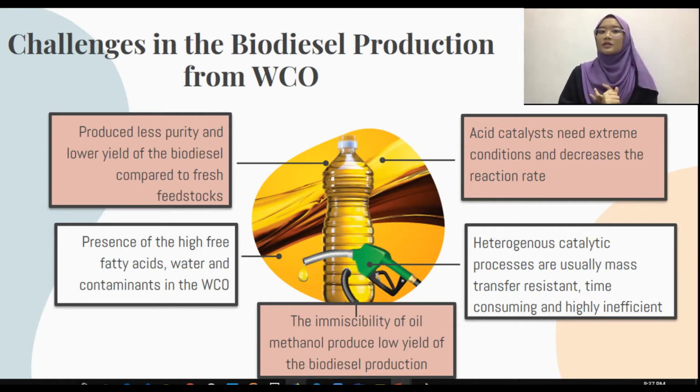Next is the presence of high free fatty acid, water and also contaminants in the waste cooking oil. The presence of the free fatty acids and contaminants will lead to undesirable side reactions during the biodiesel production. This results in an increase in operating costs due to the need for additional treatment.